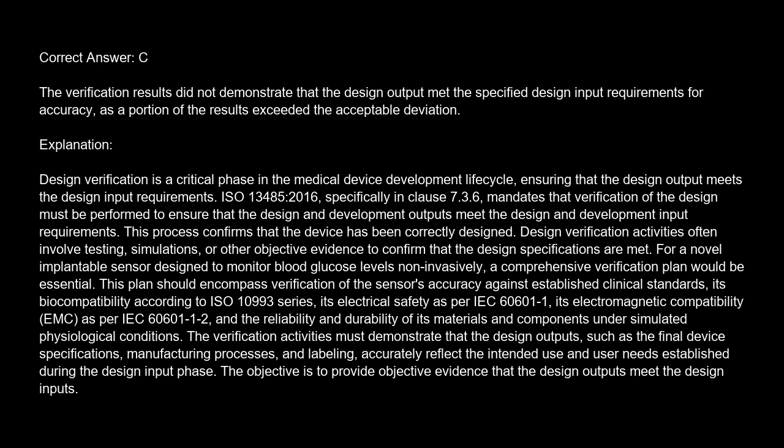For a novel implantable sensor designed to monitor blood glucose levels non-invasively, a comprehensive verification plan would be essential. This plan should encompass verification of the sensor's accuracy against established clinical standards, its biocompatibility according to the ISO 10993 series, its electrical safety, as per IEC 60601-1, its electromagnetic compatibility, EMC, as per IEC 60601-1-2, and the reliability and durability of its materials and components under simulated physiological conditions.